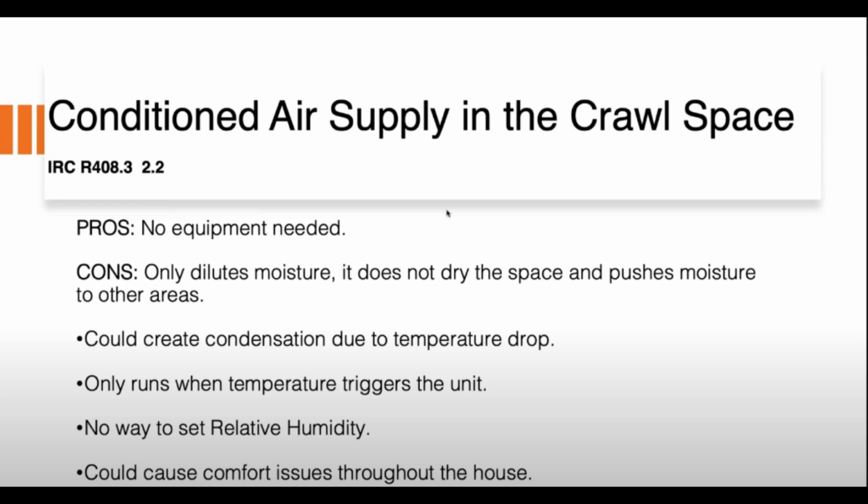At that point, we're putting cold air into a cool space. You can already have high humidity down there, and all you're trying to do is put cooler, drier air into the area. This is not a good conditioning method for a crawl space area. The only reason this is done is because it's inexpensive. Unfortunately, I see it quite a bit throughout the Mid-Atlantic and the Southeast.